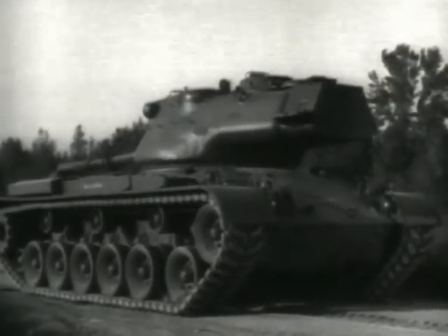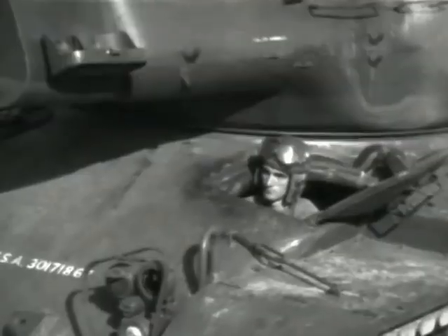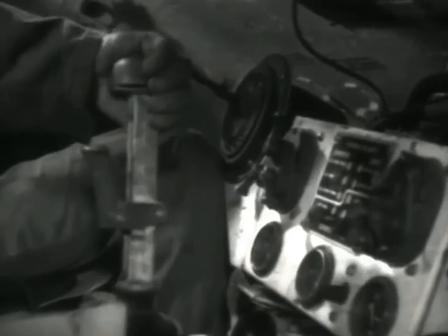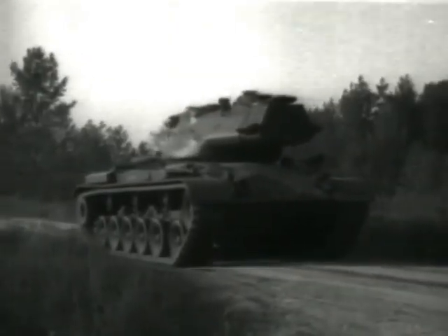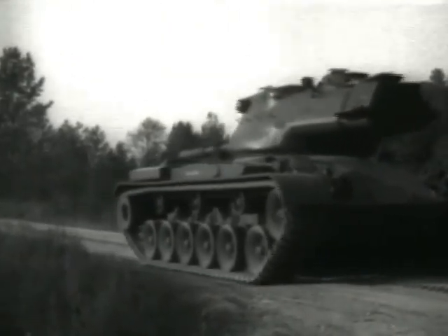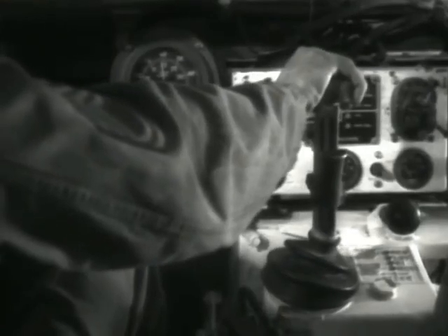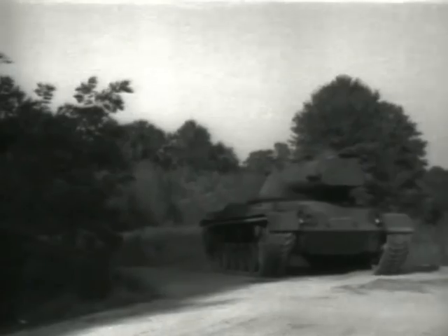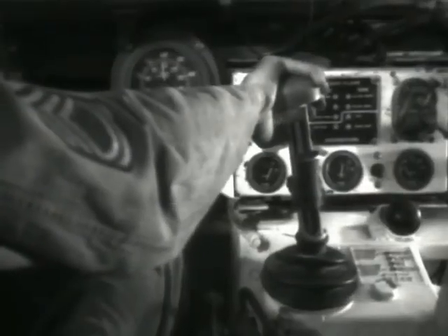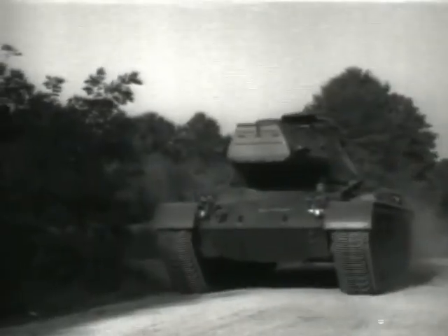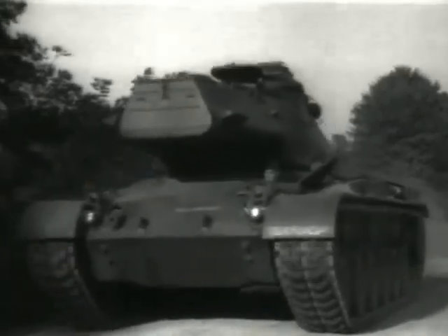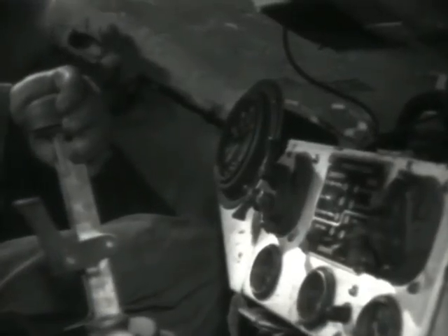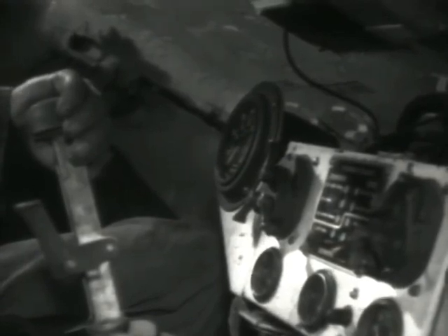Look how easy and effortless driving can be with hydraulically controlled planetary gear sets. Just a slight push of the wobble stick to the right, and 50 tons of steel obediently turn in that direction. Any movement of the wobble stick gets a response from the tank because it hydraulically controls clutches and bands inside the transmission with practically no more effort than was used to apply the clutches and bands on the model.